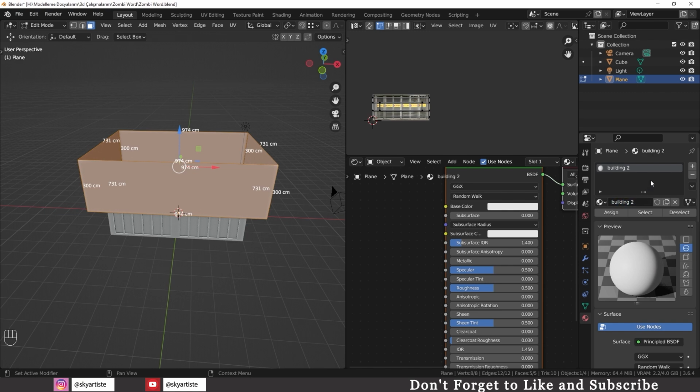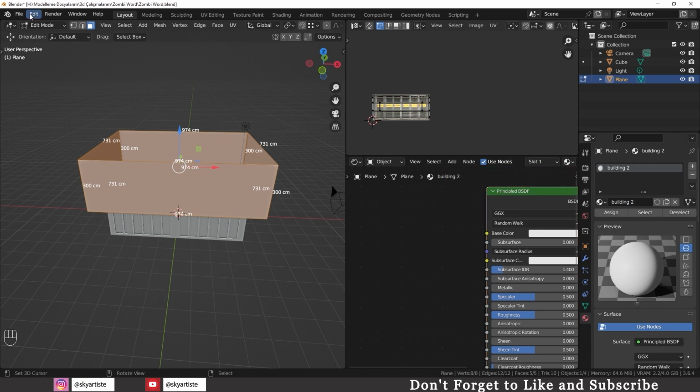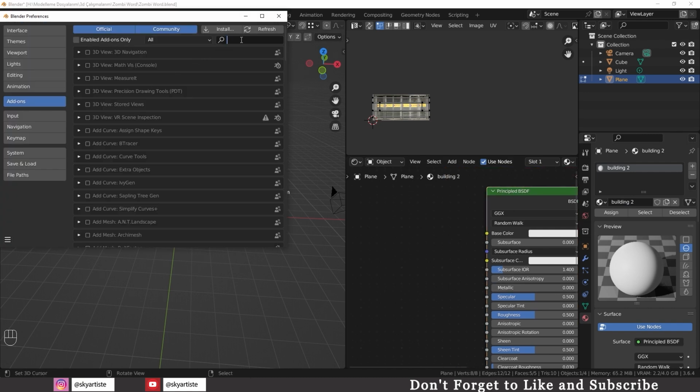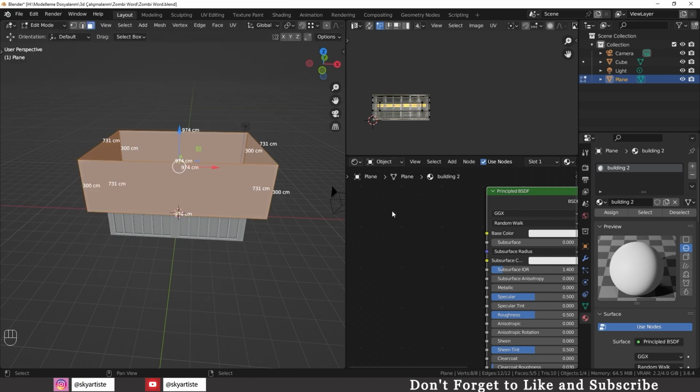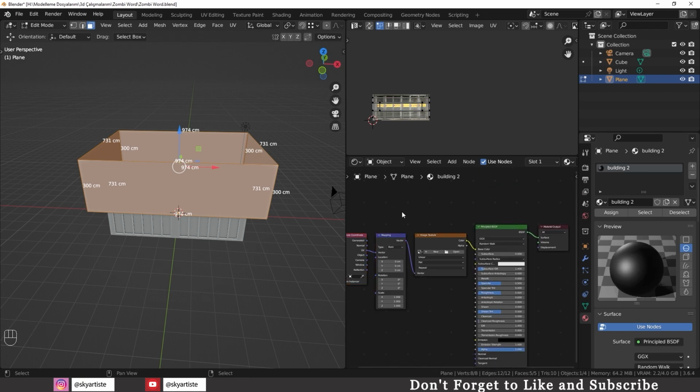In order to use the shortcut keys in the shader editor, we need to activate the Node Wrangler add-on. We go to the Edit Preferences section and search for Node Wrangler among the add-ons and activate it. The process is complete. While Principled is selected, we automatically add Image Texture with Ctrl-T.